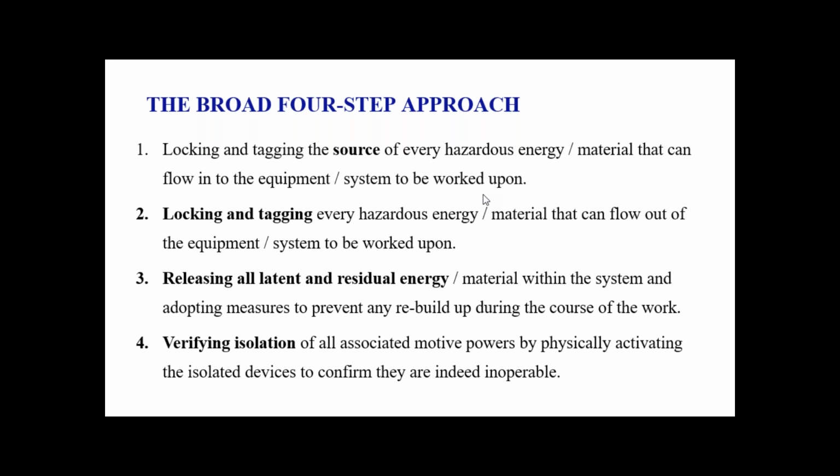The broad four-step approach for this LOTO system is: the first step is locking and tagging the source of every hazardous energy material that can flow into the equipment or system to be worked upon.